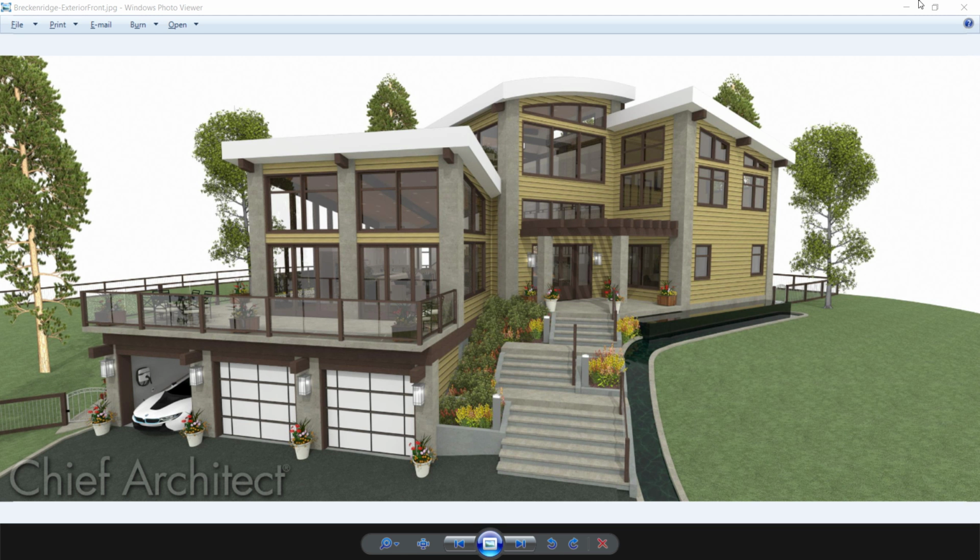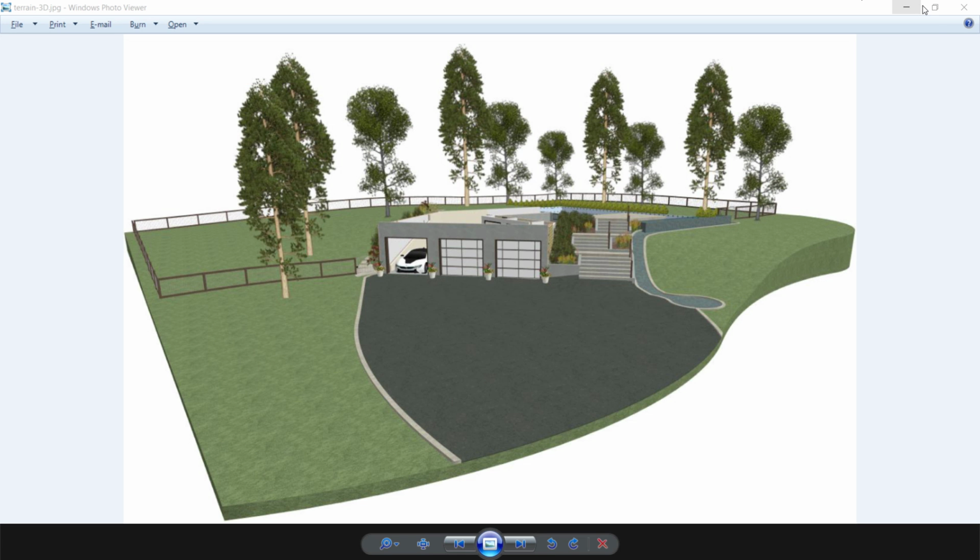Moving on to the water feature. I'm going to use the road tool because it actually follows the terrain. We have a stream tool, but that's more for a mountain stream that's somewhat irregular, and this one is a formed stream with a concrete liner. In my overview, you can see that the stream then has a pond toward the front of the property, and I'm going to use a cul-de-sac. The reason I'm using those tools is that they just follow the terrain, and I'm going to take advantage of their capabilities of doing that.